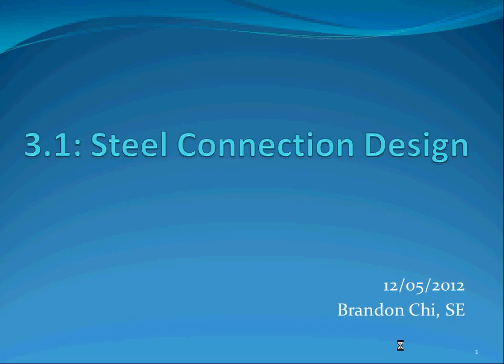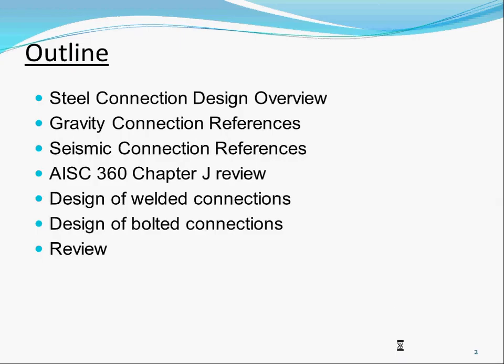Okay, this is 3.1 steel connection design. Again, this is mostly AISC 360 connection design, and for some of them we do reference other codes. When we do the welding code, we reference AWS D1.1, and when we do the bolted connections, we reference the RCSC.